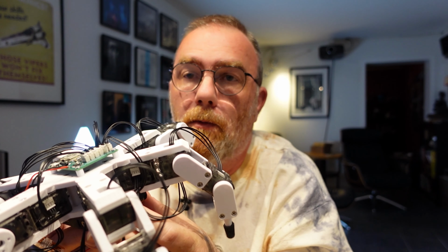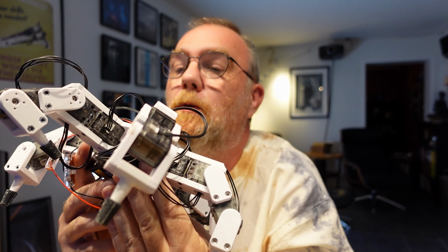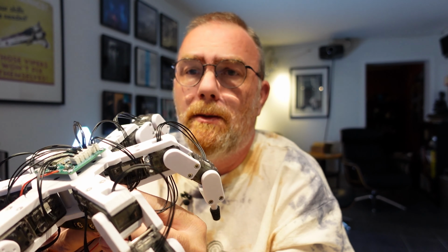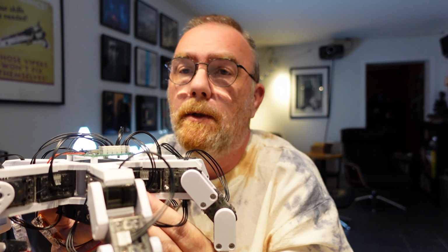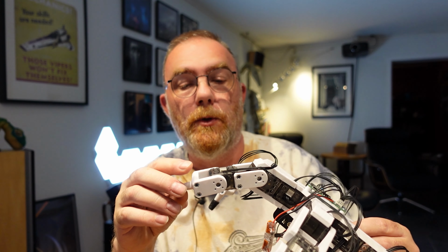I'll experiment with the number of interpolation steps and see if I can make it walk any faster. It's a bit slow, so we'll see if I can do something with that. I also have a ton of Dynamixel MX12W servos. I ordered 18 of them by mistake. They're incredibly fast servos. They don't have much torque, but I might be able to make a fast hexapod with them as long as I keep the segments pretty short. I haven't designed anything yet, but that's an option.